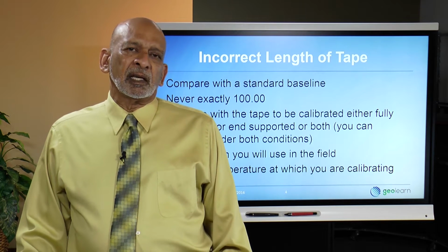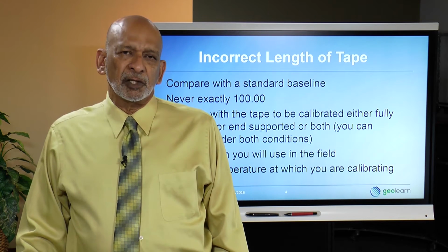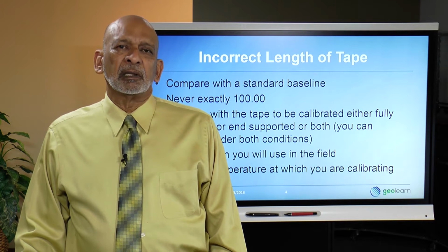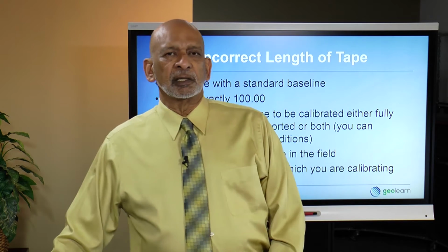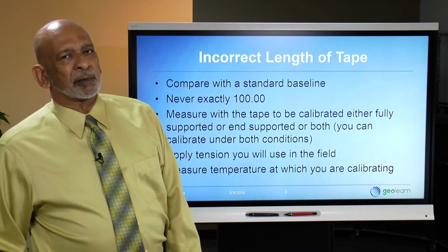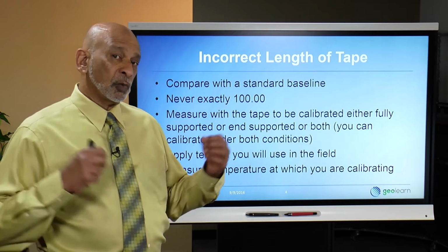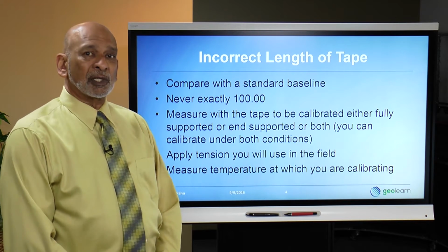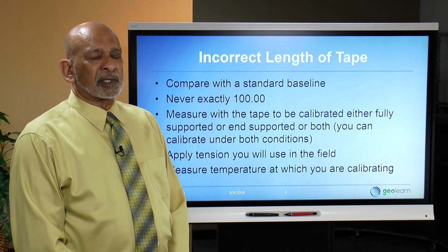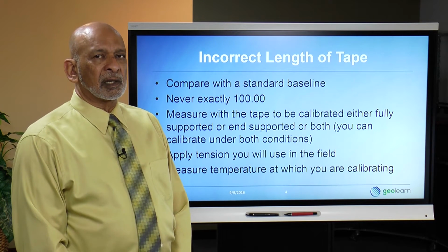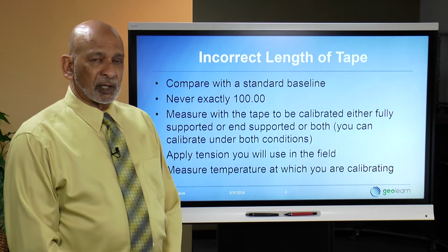And then they very carefully maintain tension and use special tools to have an extra stable measurement process to calibrate the tape. And it's very easy to measure then the distance between two reference points to 1/1000th of a foot. And I've even seen calibration lines that have been determined to 10,000th of a foot.